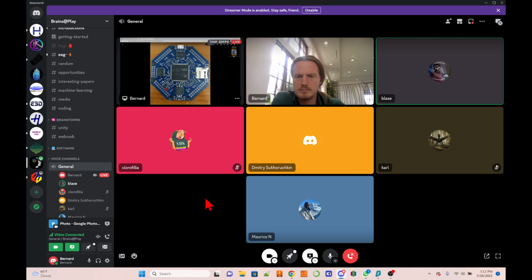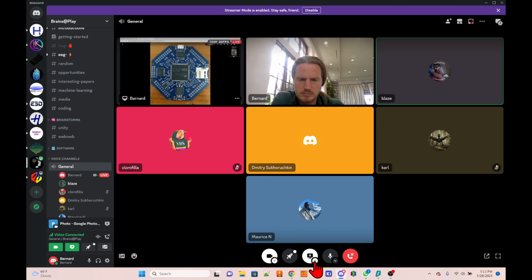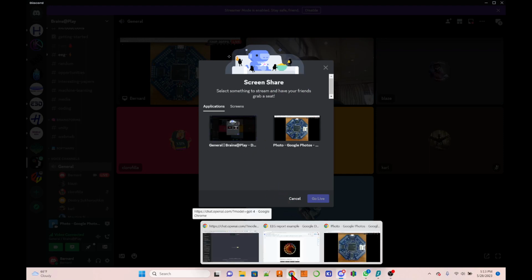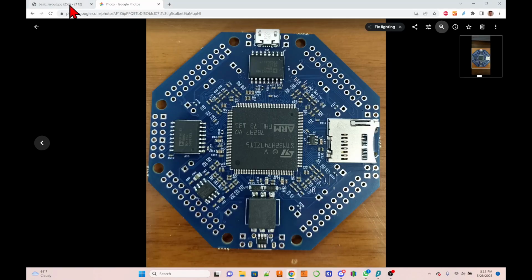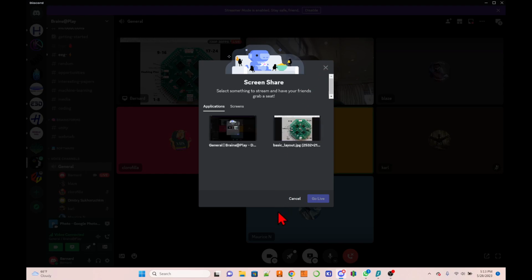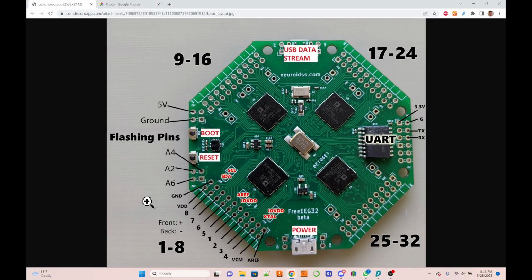Okay, so if I jump all the negatives I want to the ref, then the ref pin on all 4 amps is going to be linked together, so I can then jump on a different set of channels and get the same. Yes, it will interconnect on any of the 20 pins on the 2 connectors. INREFs are interconnected, and they are also interconnected when you stack boards. VCM interconnecting, INREF interconnecting, ground interconnecting.